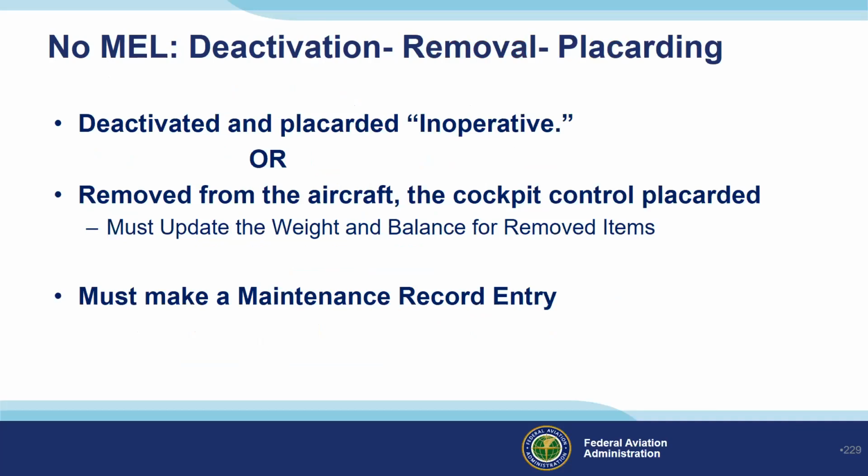If there's no MEL, deactivation, removal, and placarding. Just placard it inoperative. Or you can remove it from the aircraft and the cockpit control can be placarded. If you remove something, make sure you update the weight and balance. And don't forget the log entry.